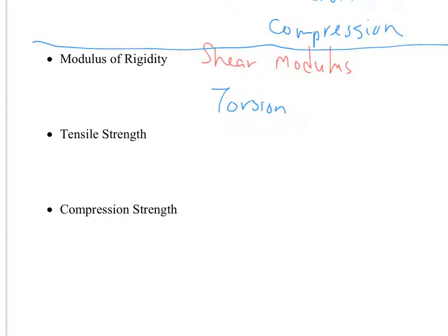Remember we talked about bending? And when we think about bending, think about a dowel rod. You're literally bending it. When I bend this, when it breaks, you're going to see that the top was in tension, it snapped apart. The bottom was in compression the whole time. So when you talk about things like bending, that's what you have to consider.